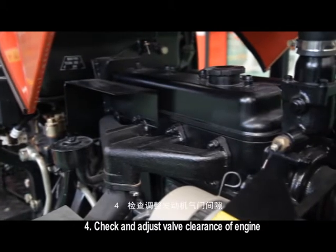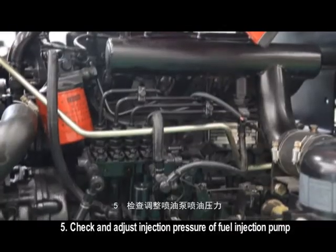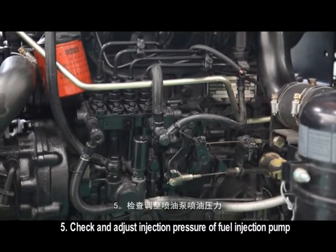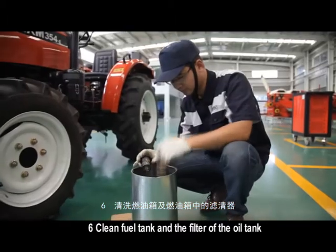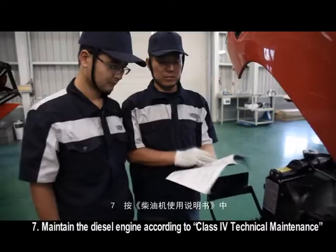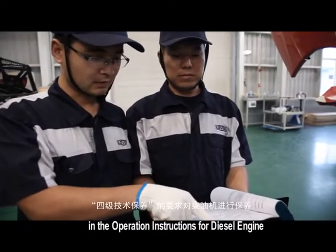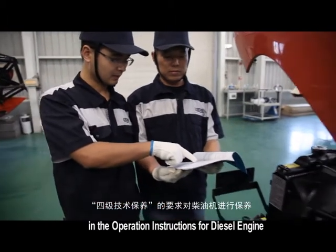4. Check and adjust valve clearance of the engine. 5. Check and adjust injection pressure of the oil injection pump. 6. Clean the fuel tank and the filter of the oil tank. 7. Maintain the diesel engine according to Class 4 technical maintenance in the operation instructions for the diesel engine.